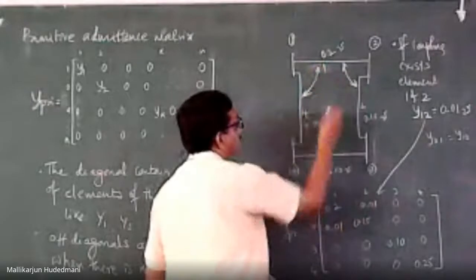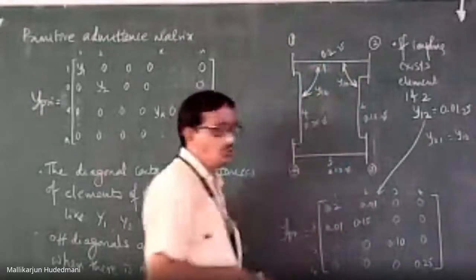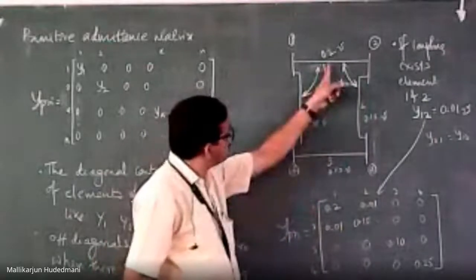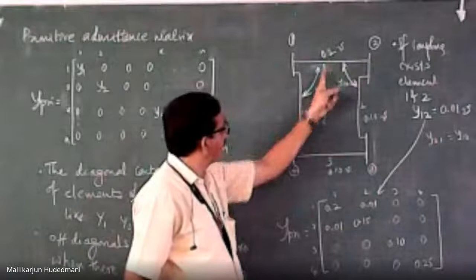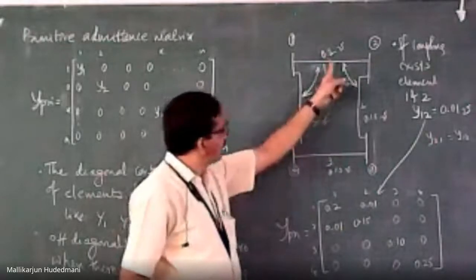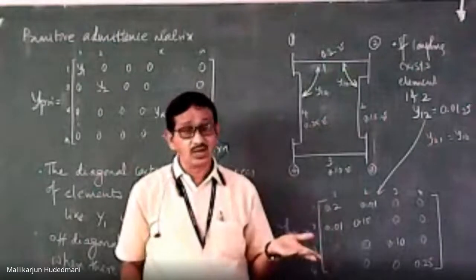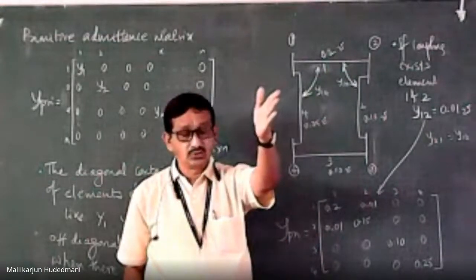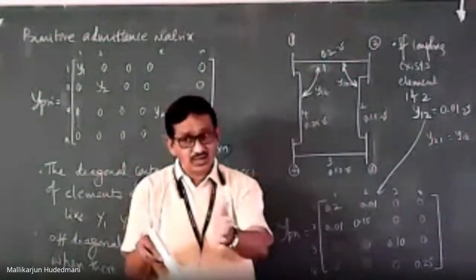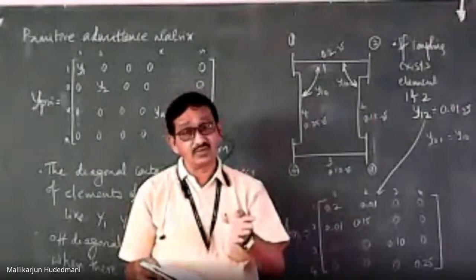Let's say this is y12, y14. You may have transmission lines, one mutually coupled with 2 with y12, as well as one mutually coupled with 4, y14. It may have a coupling with 3 also, no matter. In reality, how is that line going in the physical transmission layout? Really very close to each other? Are they really finding a mutual coupling among them, or are they isolated perfectly from each other?